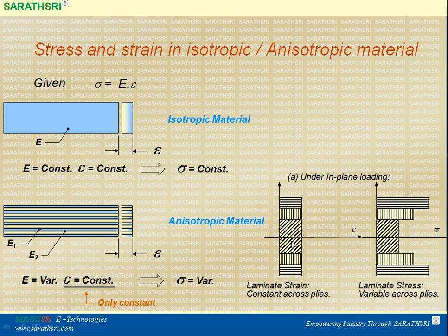The same is represented pictorially. If you take layers of laminate with different materials, which have a constant strain because of the loading, the same can be extrapolated to a different stress field across the section because each layer has a different Young's modulus.